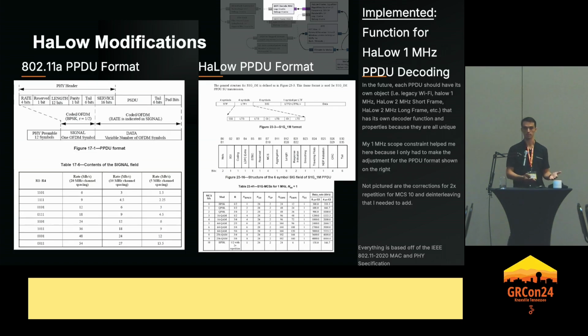So I was expecting to see that exact same modulation coding scheme in one of these signal fields. And then there's also a length field in here. So that would have provided an additional sanity check in saying, well, did my length field match about roughly how long this packet I received was?